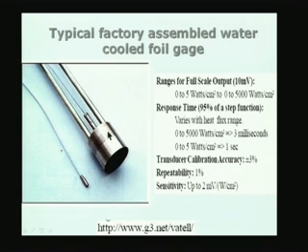The gauge consists of a cylindrical copper and there is a foil, and you are taking the thermocouple out here, the two leads, one from the center, one from the periphery is coming, and you see these two are the water cooling arrangement, the two tubes which carry the water in and out of the gauge. There is also another gauge which is not water cooled, a very small gauge for small heat flux values. You can see here we have a very small gauge without any water cooling.